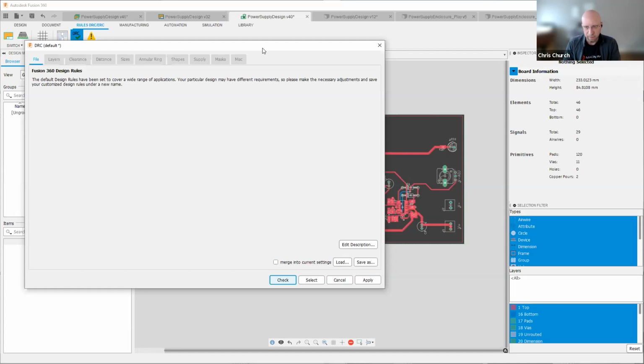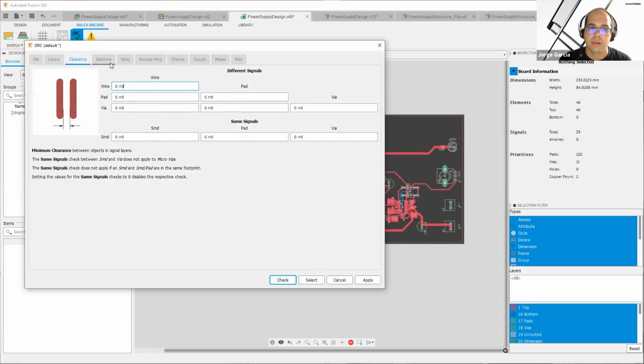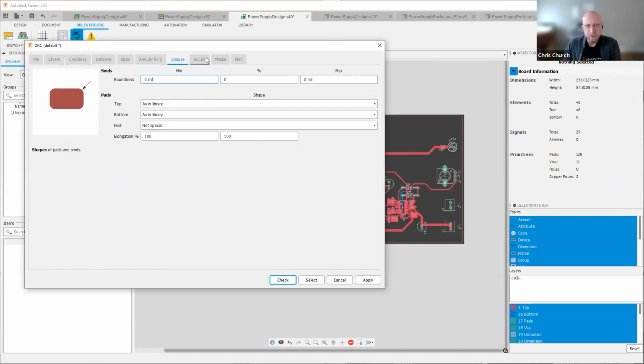And this is something we ask everyone to start with. And at MacroFab, we try to make that as easy as possible by giving you the rule files. You don't have to read a web page and type in all the values. Our focus is really making your life as easy as possible. Awesome. So that's something to keep in mind. That's a benefit that users will obtain by going to MacroFab, because you just give them the file. If you're dealing with a manufacturer who doesn't have a DRU file already made, then you have to look up their specifications on their website, interpret them, and then fill out the corresponding fields here in the DRC. Yeah, to make sure.